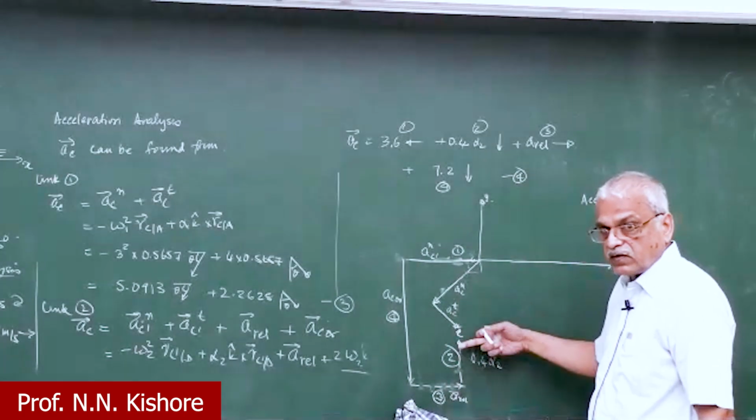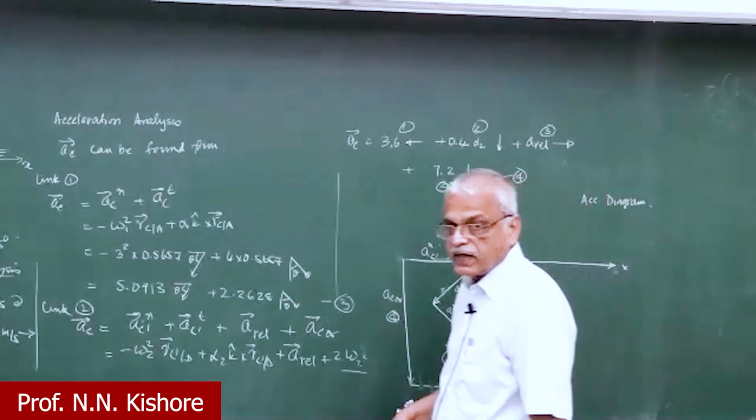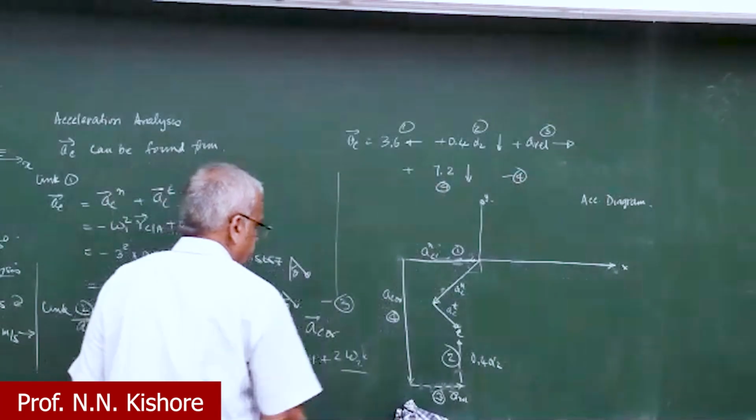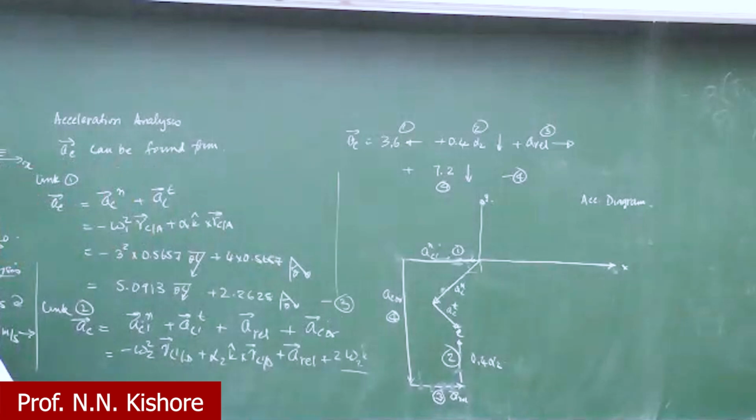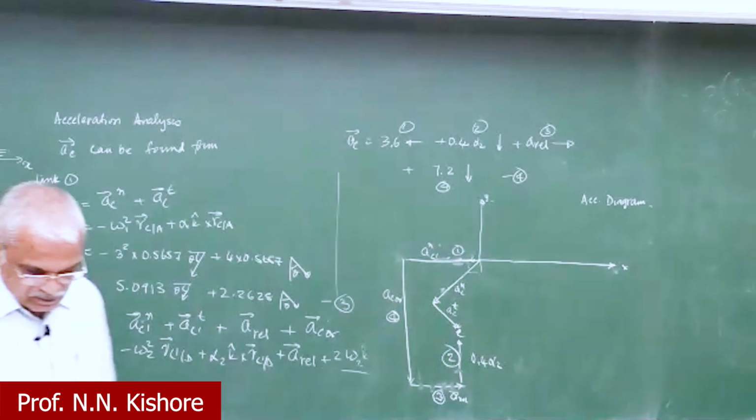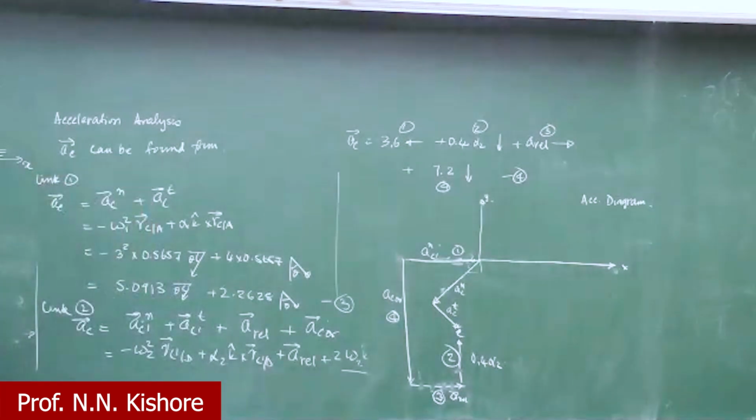And then from here, from 2, you have a vertical, and this is the velocity of C prime, to which we have to add VREL. So this is C prime and this is C. Understand? So this is a velocity analysis, in which case this is at some angle theta here.